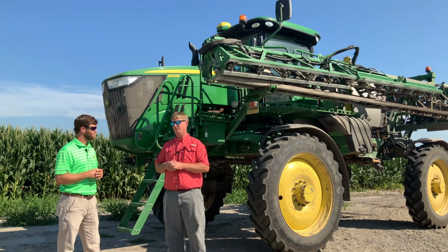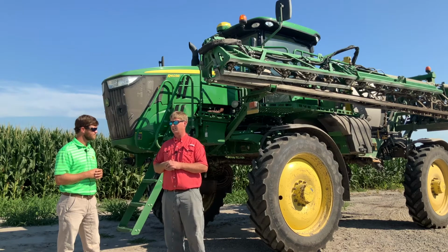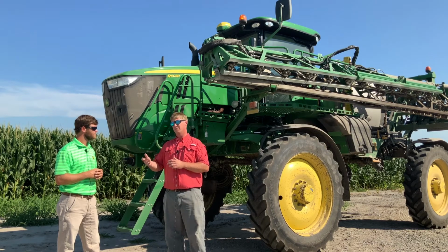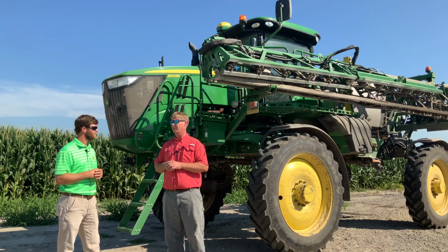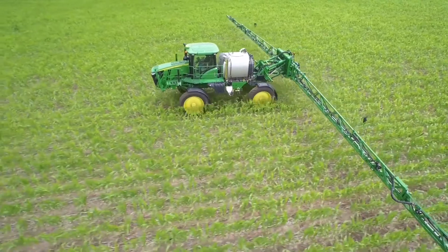With being able to control a 20-inch spacing and shut off every 20 inches, the machine becomes much more maneuverable. You don't have to pay as much attention to overlap and where you fall in your next pass. The turning compensation has proved to be much more important than we originally thought. It saves a lot on inputs, and it saves the crop a lot also.